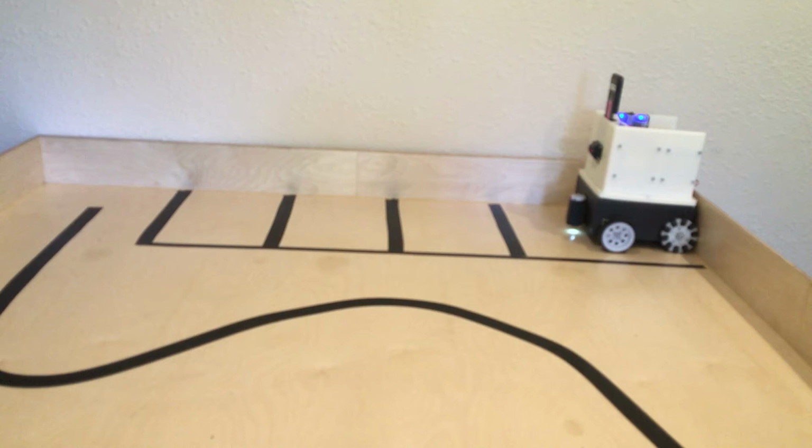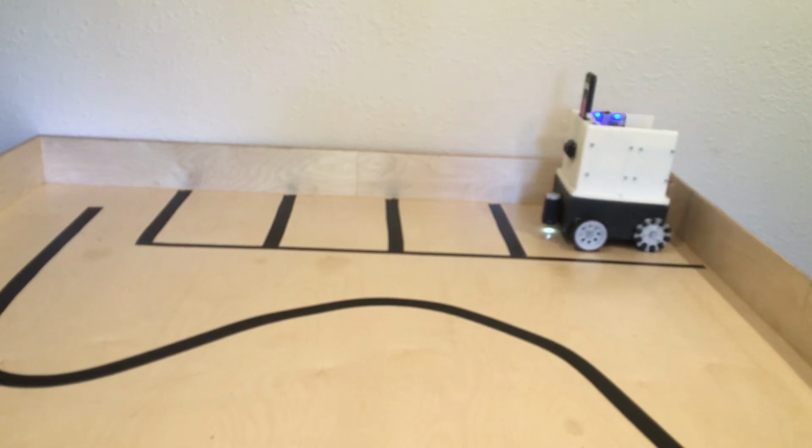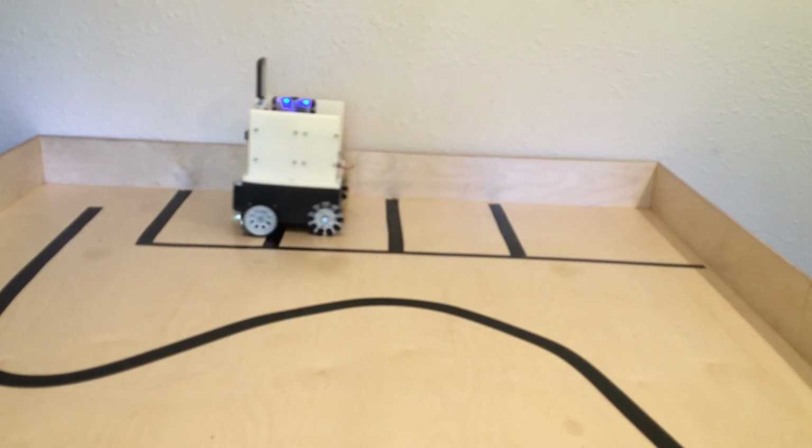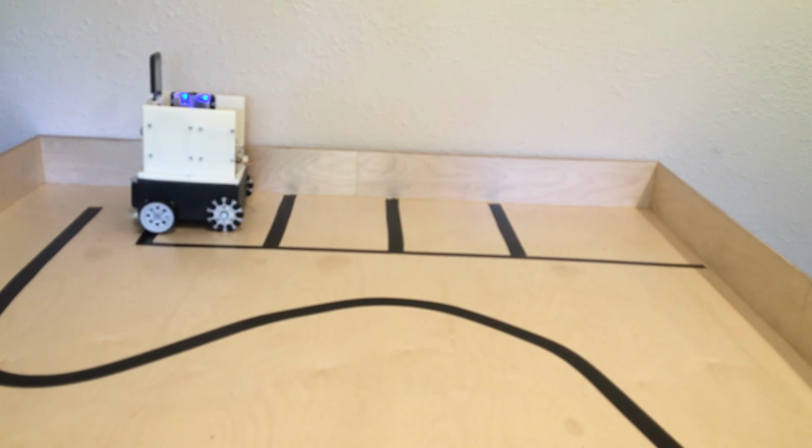Go to the driver station and make sure the FTC driver station program is running. Press the left triangle near the center of the display. You should see your autonomous program in the drop-down menu. Select the autonomous option, then press the init option followed by the run option. This will start the autonomous program and cause the robot to move forward, counting the lines as it does. When it has seen 4 lines, it will stop.